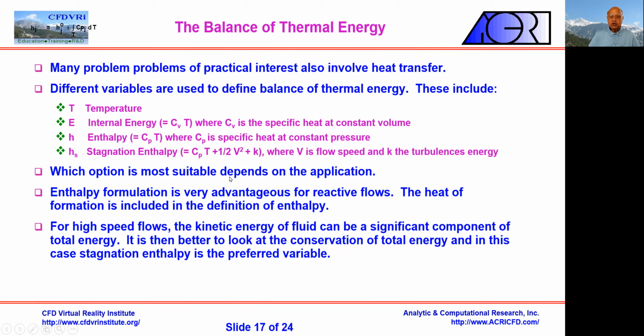So which option is most suitable depends on the application. If you're talking of reactive flow, combustion, things of that nature, then my preference is for enthalpy. The reason for that is that once you use enthalpy, the heat of formation is included in the enthalpy of the fluid component. So you don't have to explicitly deal with things like latent heat. This makes it very advantageous. Also, you don't have to deal with specific heat. It's part of the enthalpy, and specific heat is buried in there.